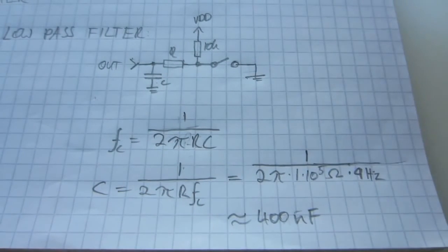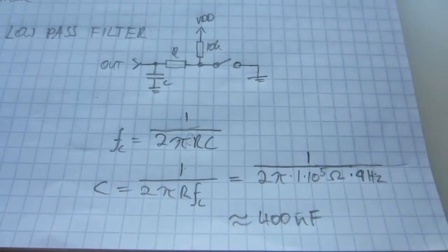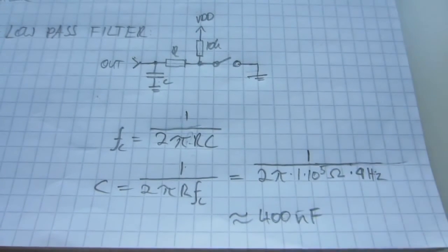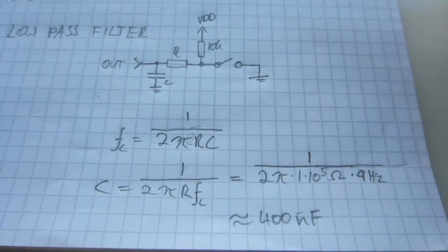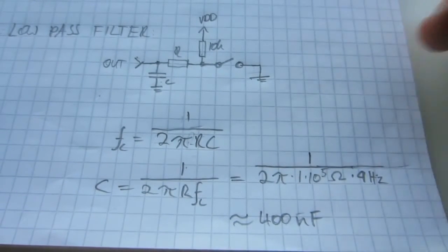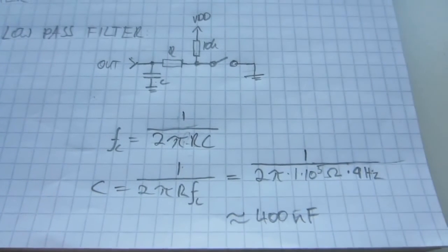But all the noise, the settling time or the bouncing of the switch, which is much higher frequency, in the hundreds of hertz, is not going to be interpreted as a switch press.